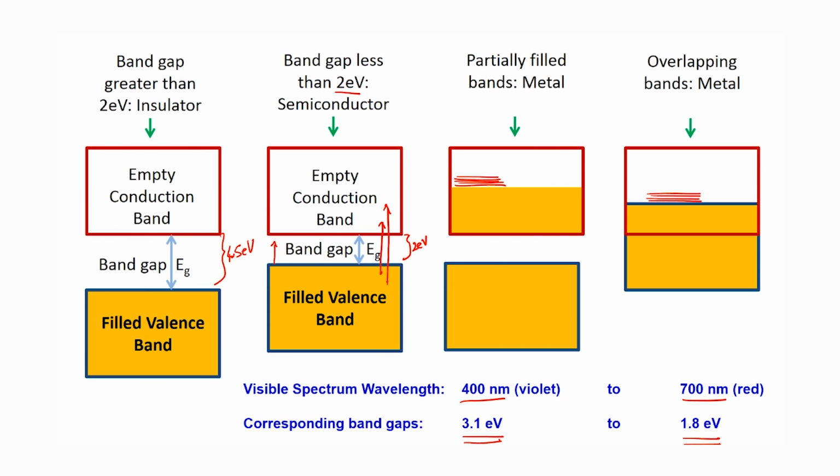But we have two things to do here. If you use a metallic surface, it gets absorbed, heat gets absorbed, and that is why we are using metallic surfaces for capturing the sunlight to pick up the heat and then use that heat for heating water or air or generating steam or a variety of things that we previously saw. But if you want to generate electricity, you have to absorb the sunlight, you have to get these charge carriers, and you have to separate the charge carriers and then use those charge carriers in some external circuit. So, you have some process that is involved there. And for that the metal then is not particularly useful to us, because it just absorbs and all the electrons are all right there, and you are not able to capture it as a separate electron that you can move into an external circuit, at least not in this general layout.